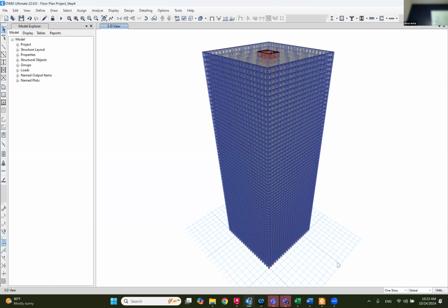Columns are adjusted, and this is the only thing that you are adjusting, the columns. Actually, some real buildings look like this. Maybe you'll say, oh, that's a lot of columns. No, a lot of buildings look exactly like this. It takes a unique shape from the distribution of the columns, and we use a unique facade that shows the window. That's all you want from a building. It's also economic because it doesn't have irregularity. When you have irregularity in buildings, it costs more, and you have to come up with new systems. But this one is cost effective, a complete direct tube system that takes all the load.